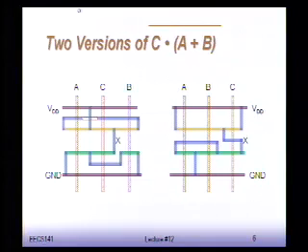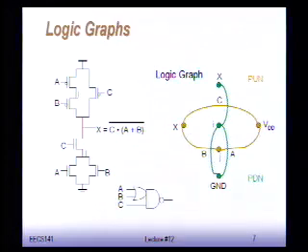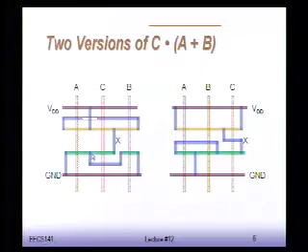Anyway, let's look at the layouts. If you look at the layouts, A and B naturally share the drain, and you want to share their drain with the source of C, okay? So you have the top transistor here at C, and it shares this node I with the parallel connection of A and B. So A and B share the node, the drain and the source, so they can be laid out as a multi-finger device. But you have the additional constraint of sharing also this node with C, okay? And so let's look at the previous stick diagrams to see what you can do.